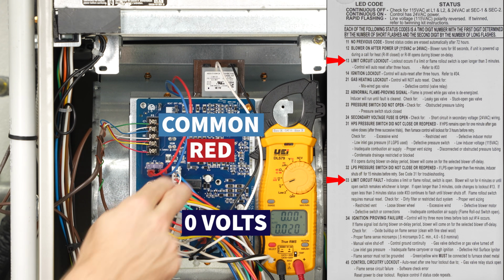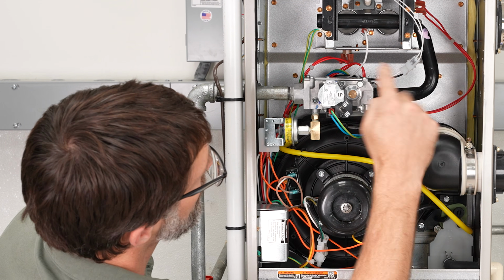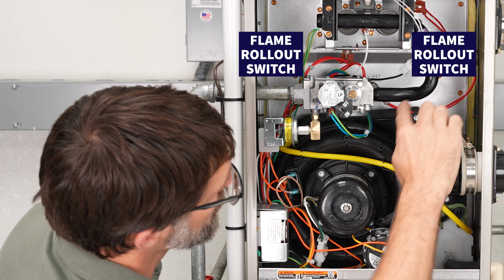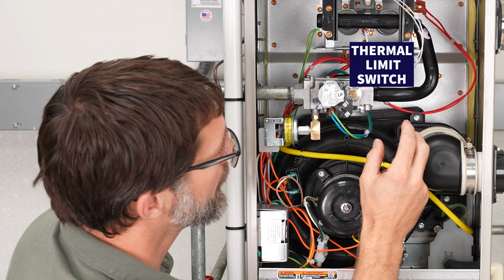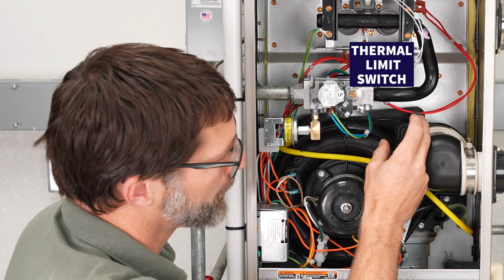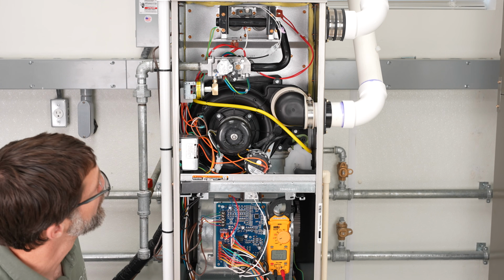Now you can see these red wires right here, we have red wires up here at these switches right here. So that's a flame rollout switch, and behind this gas valve is a thermal limit switch that's inserted into the heat exchanger area basically. And so let's get another shot at that so you can see, and I'll show you how to test up here.